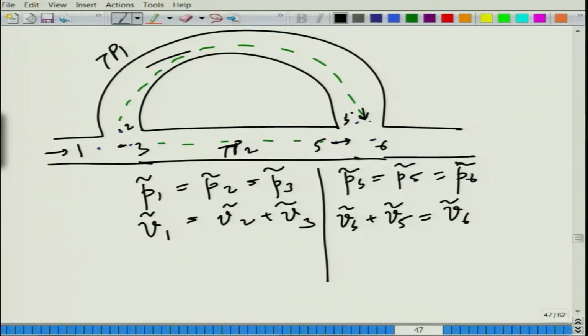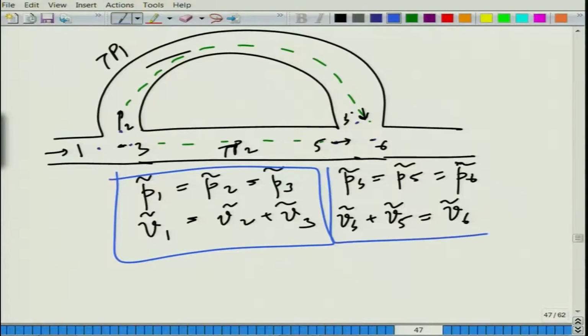Now, note that the wave propagation direction is such that the velocity at the inlet of the muffler, or at the assumed inlet, is taken into the system positive, and at the outlet the velocity is taken positive in the direction facing outside the system, that is towards this side. But we can use another sign convention also later perhaps, but for now we will probably stick to this convention, because the reason being is that we already know the transfer matrix from 2